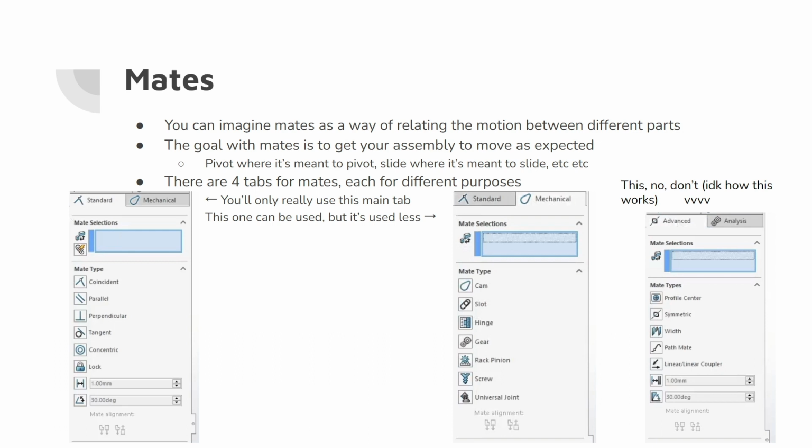So you can specify all that with that. Angle, limiter, yeah. You can flip the mate alignment. By the way, quick note, instead of using this all the time, just click on the surface of one thing you want to mate to, and shift click on another, and don't move your mouse. The mate options are going to show up below after a half second.